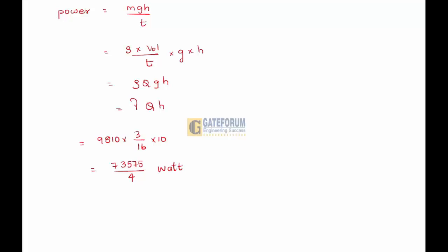But he has given horsepower of pump is power by 746 into efficiency. Power is 73575 by 4 into 746 into 0.8.